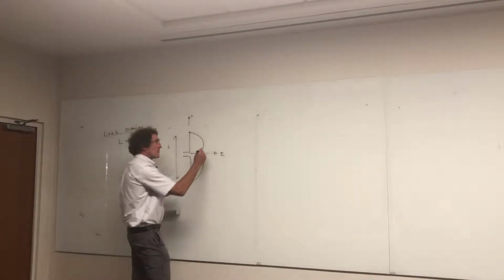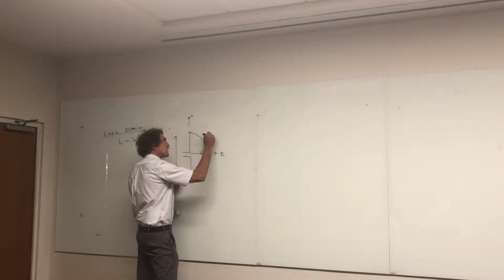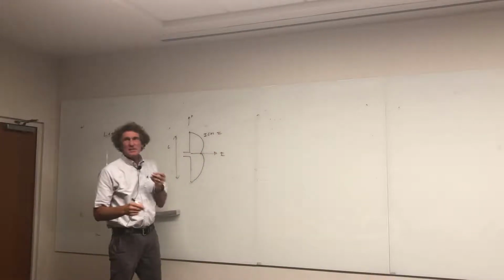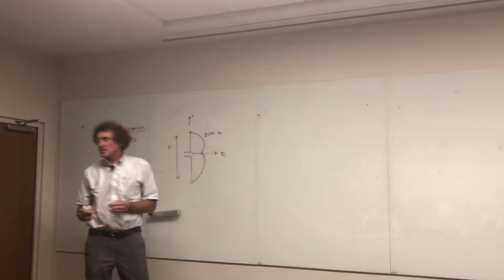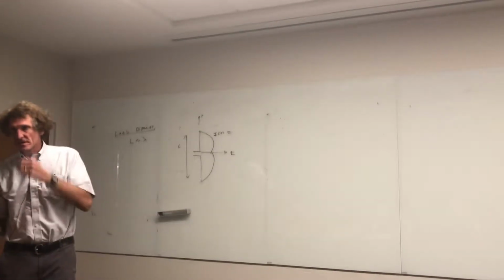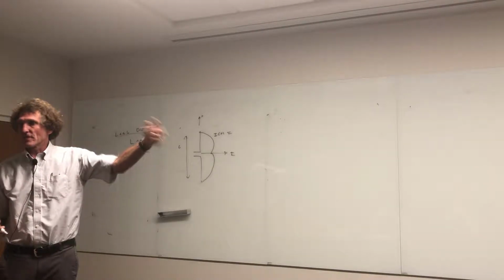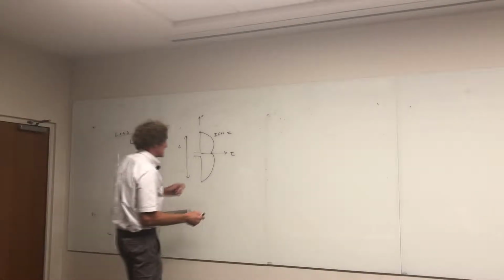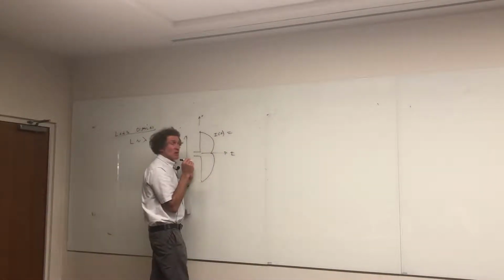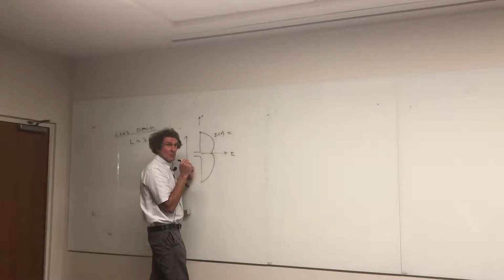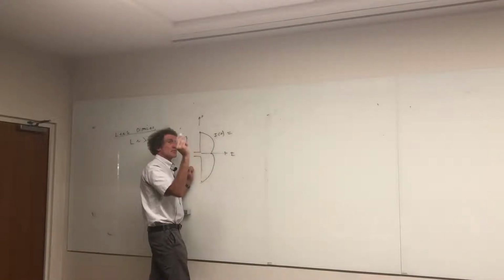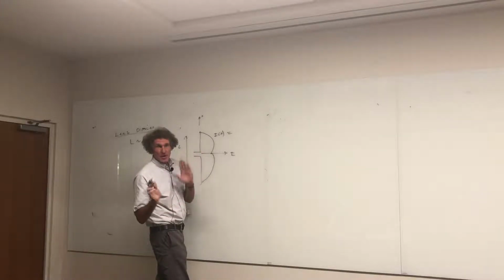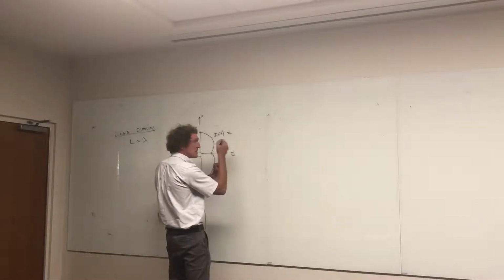Now this current profile, this is an I of z. There is not a closed form solution for this. This is developed by consistent iterations, and I can only tell you that it's more complicated than it would seem to get this, because the way you solve this is solving Maxwell's equations with boundary conditions on a finite thickness antenna. And what you end up doing is getting a solution that keeps on getting refined and better and better. What we've got here is an approximation for the current on this.